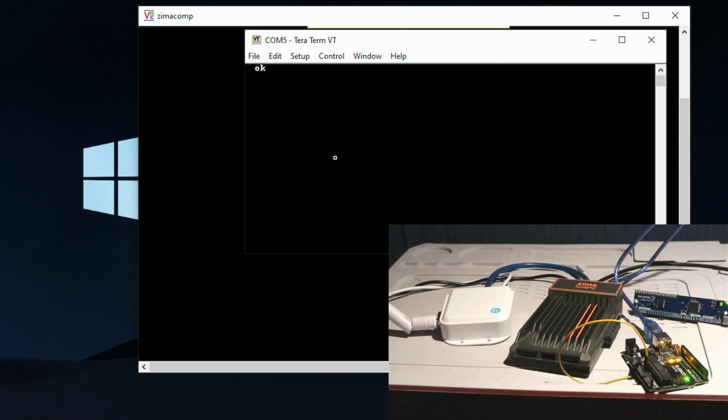And if I just type in FF LEDs, you can see that I can just blink some LEDs. Type in 1 LEDs, you got 1 LED. And we can just do things like that. So we can remotely check in on things. I could have this Scamp 3 board be running things. I believe it has a temperature word, so we can get the temperature. And we can put this in a loop and get the temperature from the Scamp 3 board.